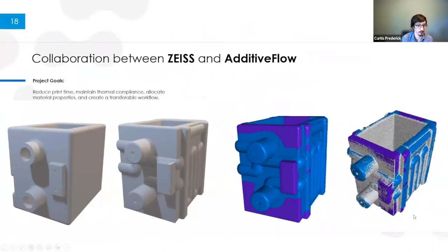So here we have the stages we went through. The original STLs on the far left doesn't have optimized regions, and it's got extra material. Then we move to the next stage. We've got that removed volume. We've left some areas there for mounting and machining. And then we've got these stages where it's been allocated to regions that need to be faster, that aren't important. And then our final STL comparison to printed part that's been CT scanned. So we know that it worked out in the end.